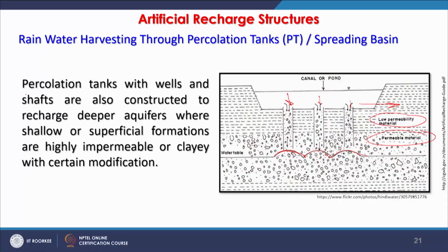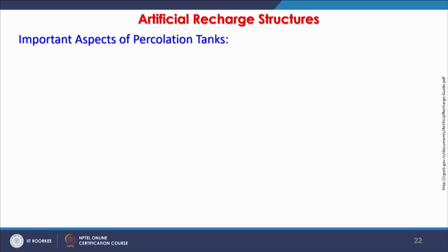Then at the bottom of these tanks such wells can be created. And this is what is shown here, that percolation tanks with wells and shaft are also constructed to recharge deeper aquifers where shallow or superficial formations are highly impermeable or clay, with certain modifications.